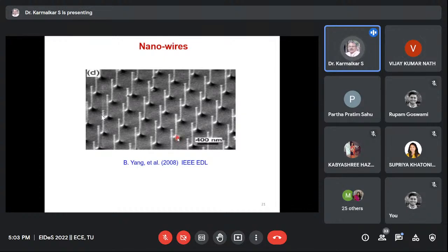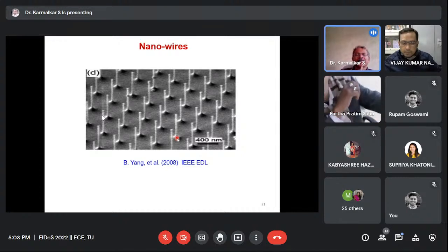What you have to do is take a substrate. You have to create small islands like this, thin circular things, like dots on a substrate. Women will understand it better: you have that paper on which you have small bindis, right? When you buy the bindis, that is how they look. There is a cardboard, and on that you have small circles dotted like that. Exactly that is how the substrate will be. Then, using a chemical reaction, on those dots or bindis you grow silicon. It's the same as chemical vapor deposition. Only in those areas the silicon will grow. That is how you create these wires.